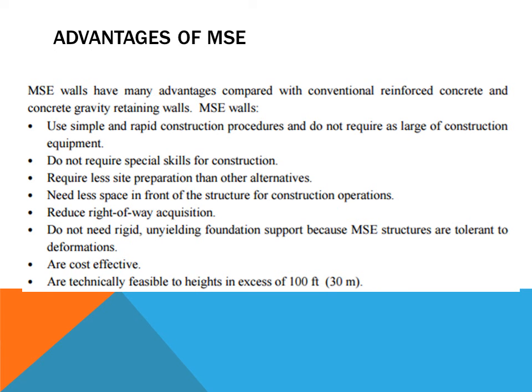beneficial to certain projects? Okay, MSE walls have many advantages as compared to the conventional reinforced concrete and gravity retaining walls. They use simple and rapid construction procedures and do not require as large construction equipment. Then they do not require special skill for construction, and they require less site preparation than other alternatives.